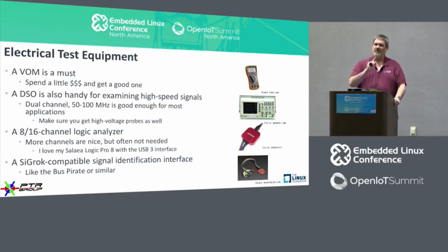The problem with LCD-based meters is oftentimes the event that I'm looking for happens so quickly that the screen can't update fast enough. There's a voltage change there, but it's so quick that I can't tell what the voltage change was. If that is the case, and oftentimes it is, then we drop to a digital storage oscilloscope.